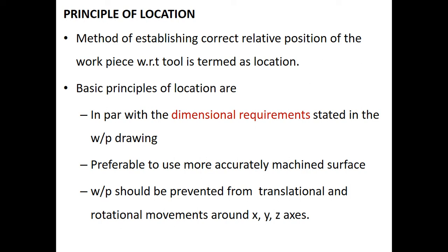Point number two, it is preferable to use more accurately machined surface than less accurate surface for location. So it is preferable to avoid undulations, which I have mentioned before.